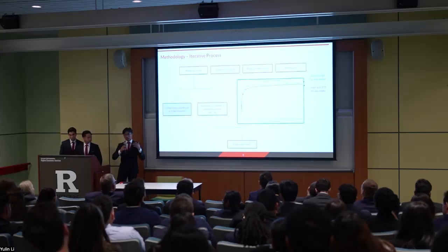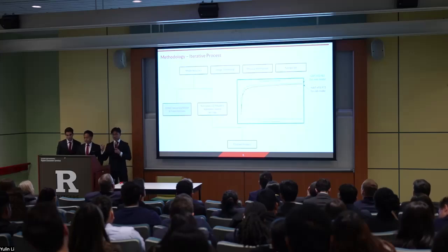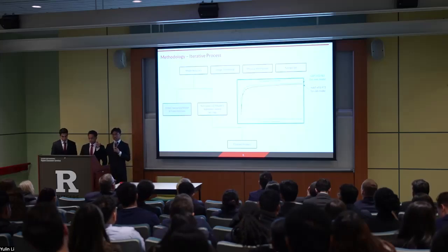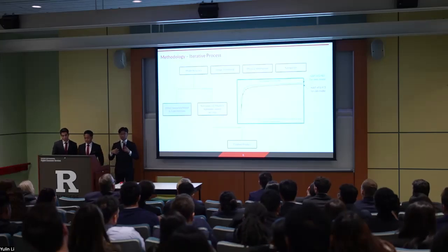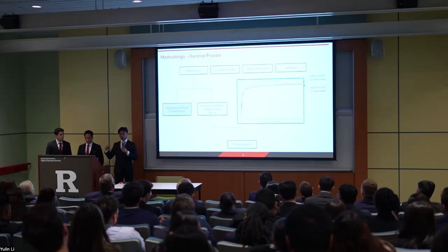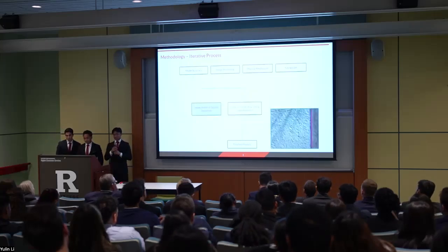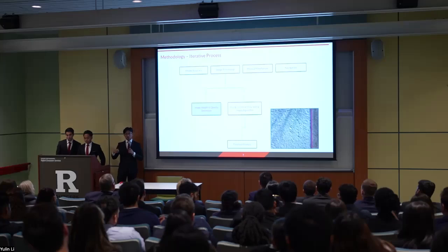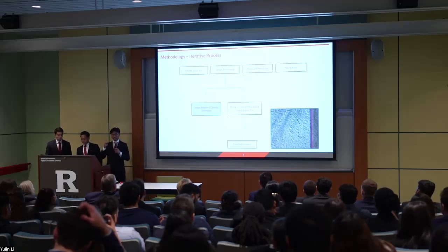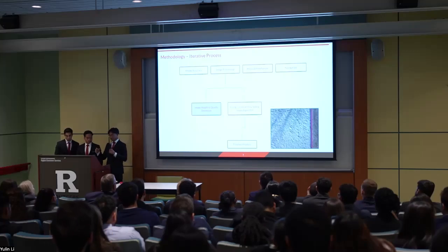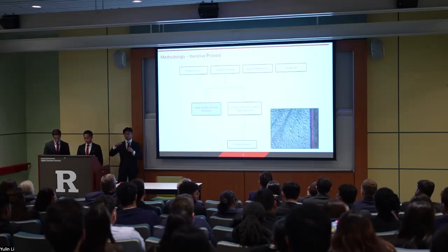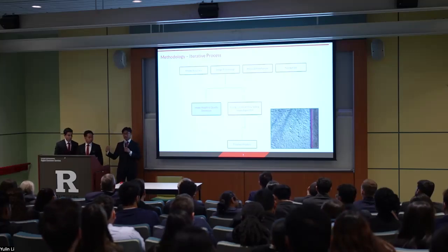So we initially started with an inaccurate model, and we refined it and retrained it to have 99% precision and 96% recall on our object detection model, as well as adjusted the camera settings on the drone to ensure we were mitigating false positives. Through image processing, we created flying constraints for the drone, so we weren't flying it too high that it didn't see the garbage on the beaches or on the testing area, as well as we weren't flying it low enough that it was hitting any obstacles.